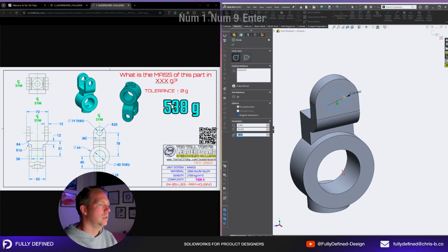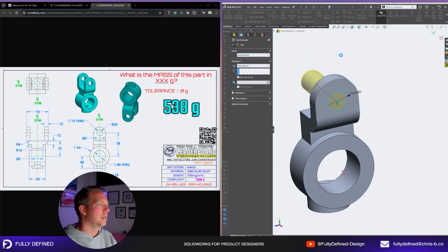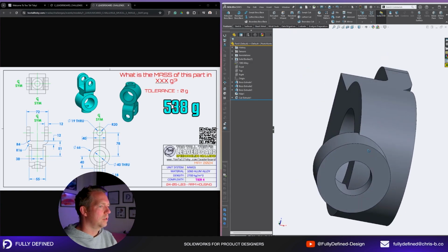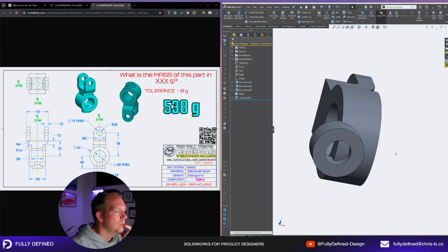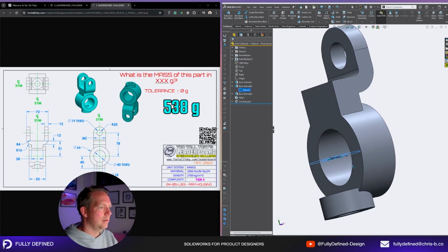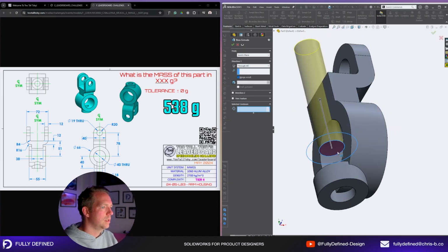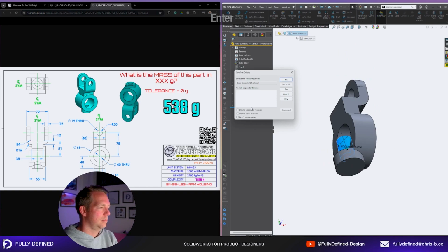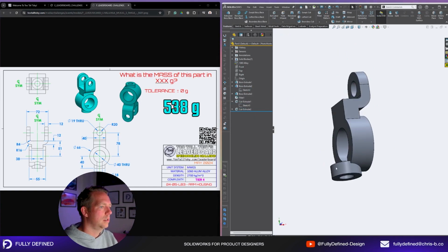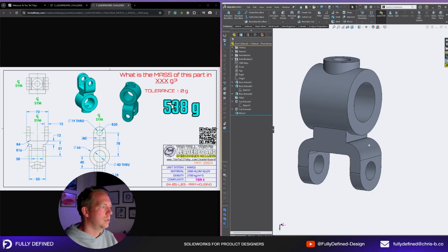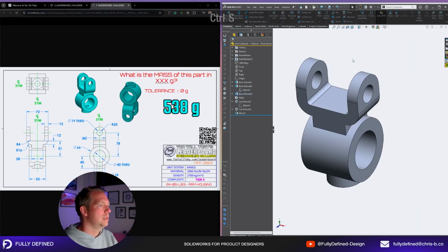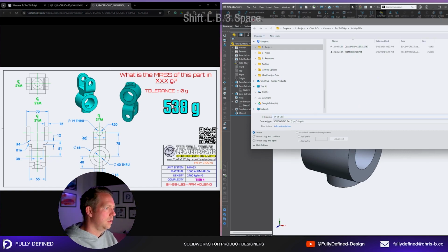And then a hole, 19, maybe a hole wizard would be quicker there. And yeah, you can see I've got an issue here. That's not going to work. That hole needs to be done after. I have to do it twice anyway. So it's just selecting that, and this time select contour down. Not a boss, it's the wrong one. Extrude, all right. And then we can mirror, it should be correct. Nope, what are we missing? Radius 16. Let's save it and we can find out.